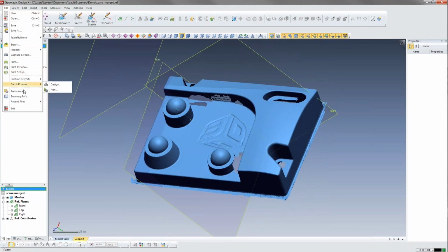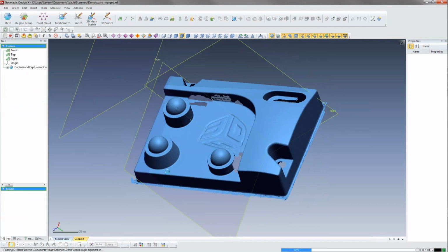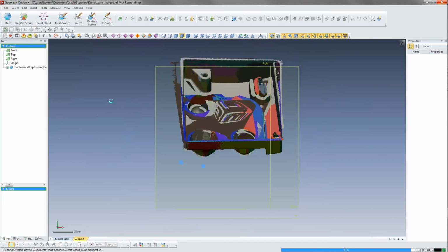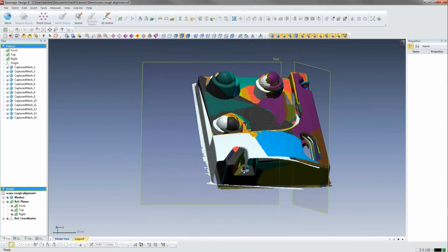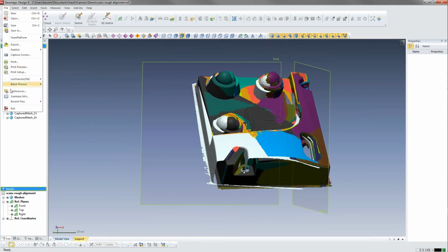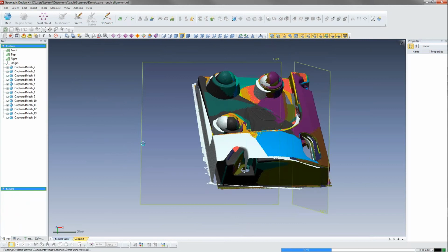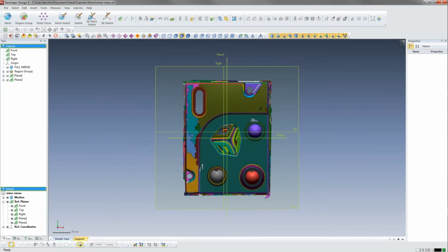After we get our surfacing done out here, we get all those meshes merged, then we can come out. I think I just actually clicked on the wrong thing there, and we're going to go back a step. Yep, there's a rough merge together with more scans. So I'm going to come in here with views. So after we get the surface created, then we want to pull this up so we're looking at it flat.